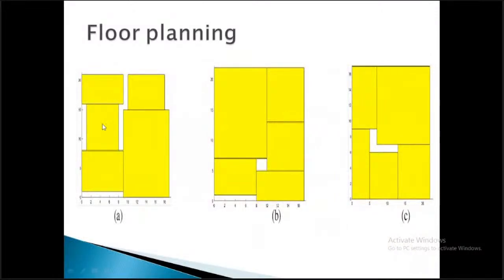You can see here, let's see, 1 2 3 4 5 blocks are there. How will we place these blocks so that our area will be more optimized? You can see the same blocks are placed here in 4 ways. These two seem more optimized as compared to this one. These are different kinds of algorithms, heuristics and others, that the tool itself uses, and it gives some output estimation based on the input netlist. It gives what is the maximum optimized area we can get.